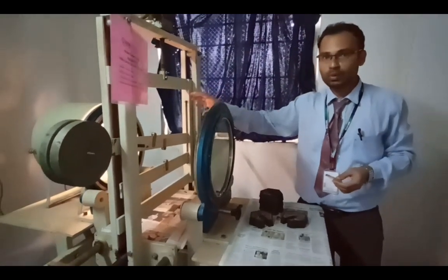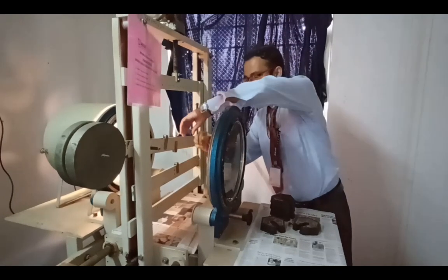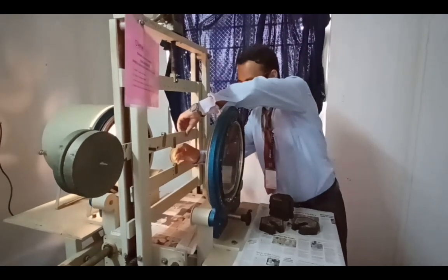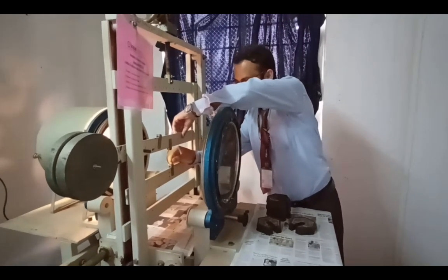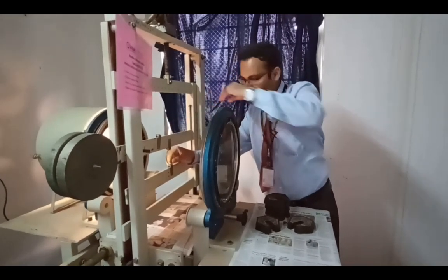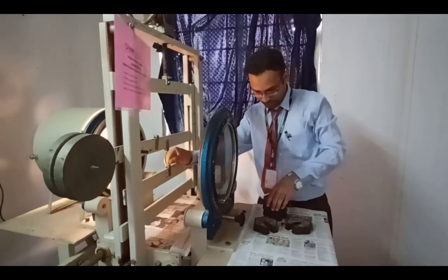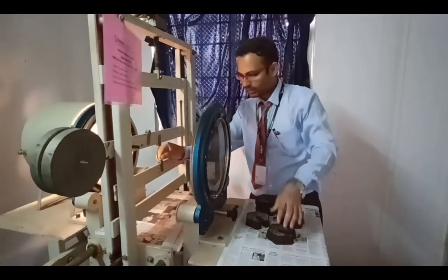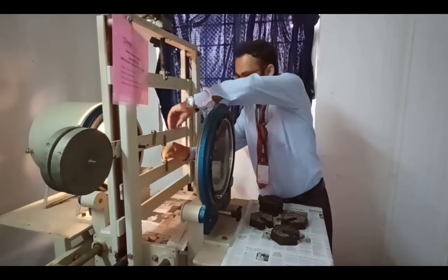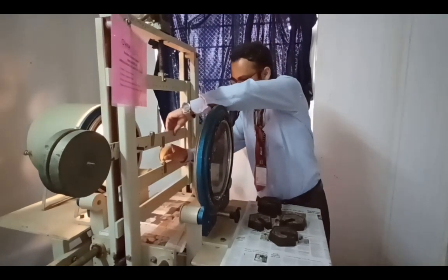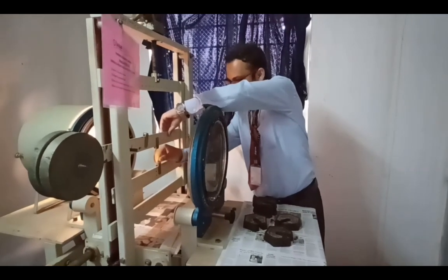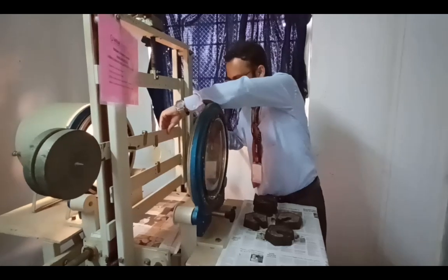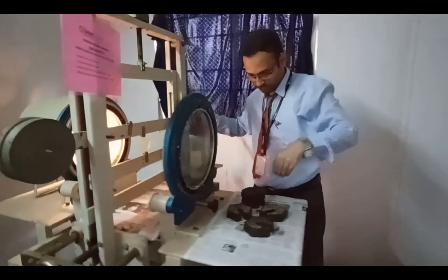Now I am keeping the circular photoelastic specimen in this. Exactly, you fix it in the middle. This is a circular disc. Now you are going to apply a force on this element with the help of some load. Here we have a 5 kg load, each load being 1 kg. First you fix this photoelastic specimen properly, then you apply compression force with the help of this load.